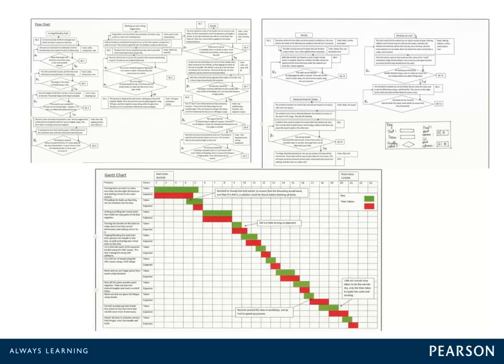It is not sufficient to state, for example, cut legs to length or drill holes. More information is required, such as cut 4 legs to lengths of 400 millimeters using a tenon saw, or drill 2 20-millimeter holes using a flat bit and pedestal drill.